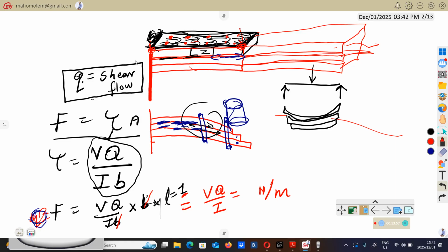Right, so at some point we're still going to calculate the pitch. If you put the nail here and nail here, we don't just put the nails anywhere, as you wish. We have to calculate the pitch, the distance between this nail and this one, the distance between this one and this one. This thing, we're going to call a pitch.